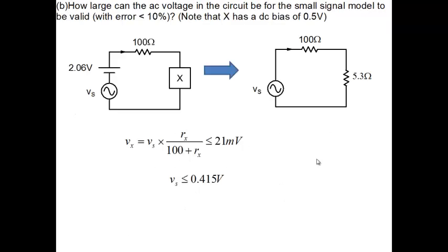Okay. So if you look at this particular part here, normally a problem would be of this kind. Normally a problem would be that I have an element X and resistors and other things and a power supply here and this one here. And our interest is in knowing, let's say, how much is the current flowing in X due to this Vs. So we treat Vs as an incremental source. And so what we do is we have to take out Vs first.